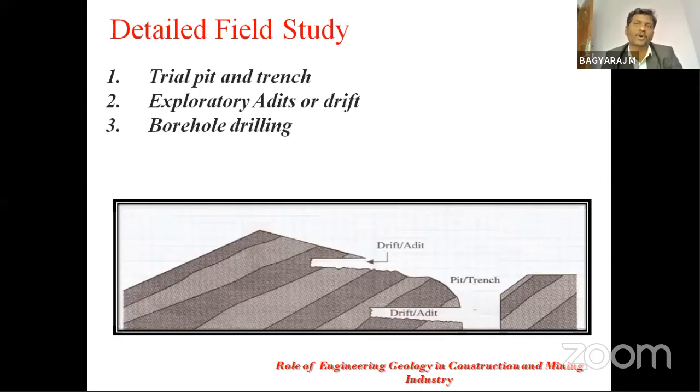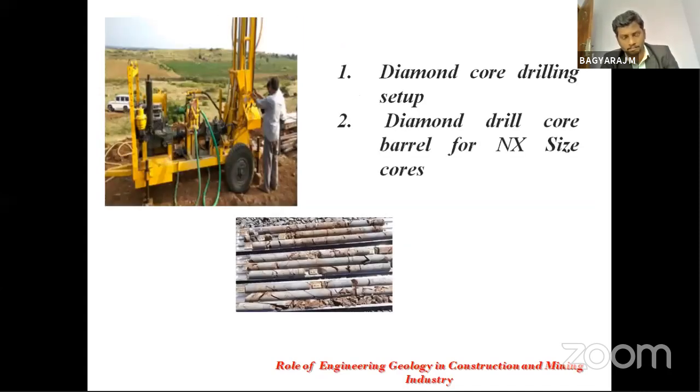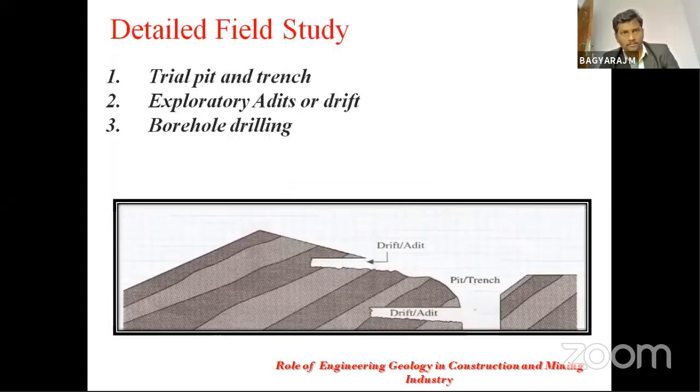But what is important as far as engineering geology is concerned, we work out parameters called core recovery percent or rock quality designation. Depending upon the project, we can go up to 50 meter depth. Most civil engineering structures are not beyond this depth.